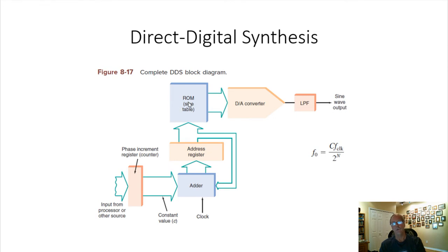Basically, you run a broken sine wave through here, and when it goes through the transmitter and the antenna system, the way that breaks that sine wave will actually fix it. So if you have a bump here and a dip here, it comes out completely straight, a completely pure sine wave. So that's called pre-distortion.